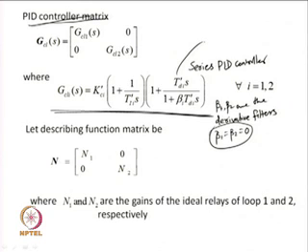I dash. Okay. Now, the controller in the matrix form, and that too in diagonal form, is given by GCL(S) equal to GCL1(S) 0 0 GCL2(S), where GCLI(S) will be equal to KCI dash times 1 plus 1 upon TI dash S, times 1 plus TdI dash S upon 1 plus betaI TdI dash S. Okay. So, we are using the series form of PID controllers.